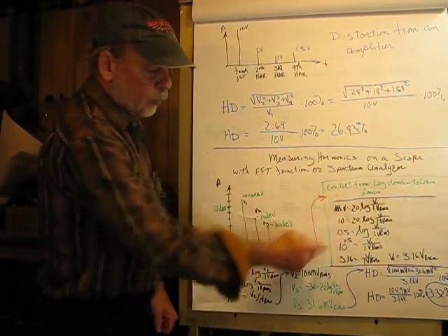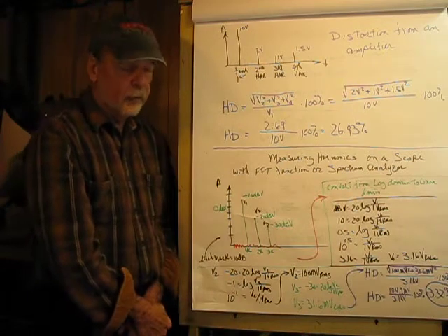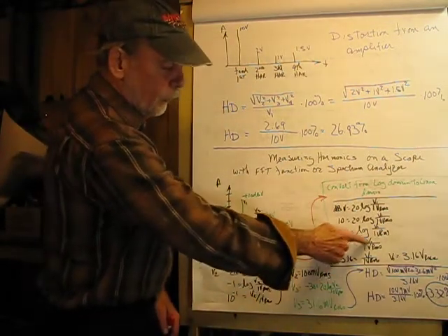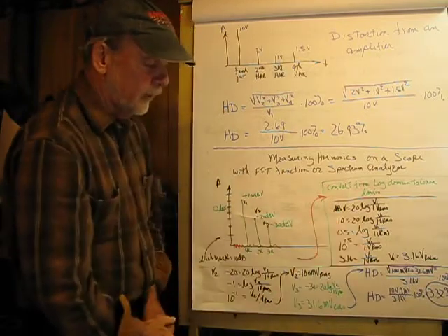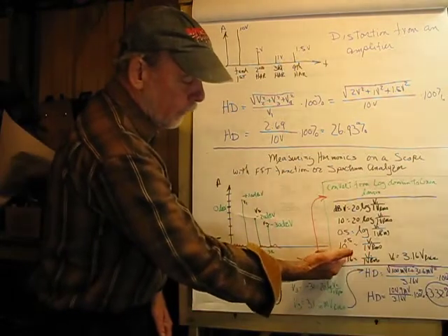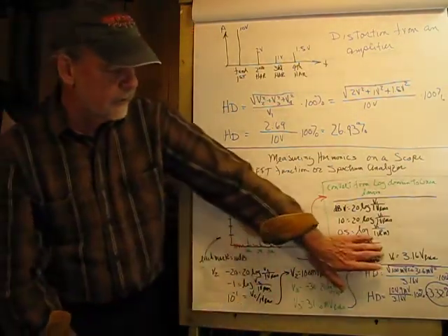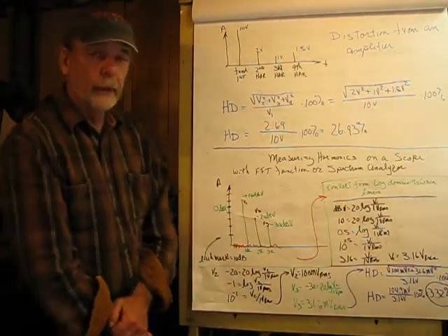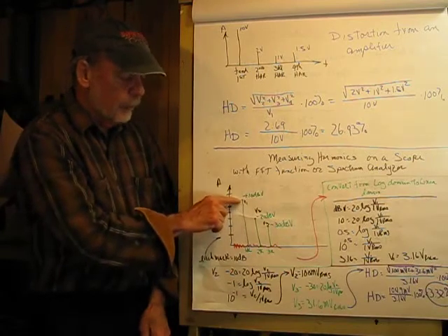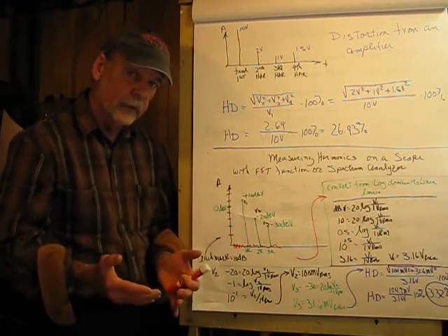Dividing both sides by 20 gives us 0.5, and then we take the inverse log of both sides, which would be 10 raised to the 0.5 power equals our voltage times 1 volt RMS. Now the easy part is all we do is multiply this guy by 1 volt RMS, and what we see is we get a voltage of V1 of 3.16 volts RMS. So that would be this voltage here if we were to measure it in the linear domain.